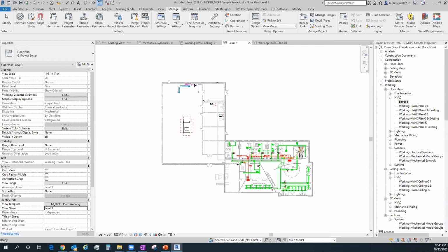But literally when you upgrade a template over and over and over again, you're not actually getting all of the changes into the new version. One of the things that I found early on, from 2013 to 2014, was that 2013 added a D loop leader for arrowhead types. The dot leaders, closed-end leaders, things like that, were all still there from the previous versions, but the D-loop leader never arrived in our projects, even up in 2016. I was like, I know we have a D-loop leader, and that works really great on pipe objects or control diagrams and things like that. We just didn't have it in the project template.